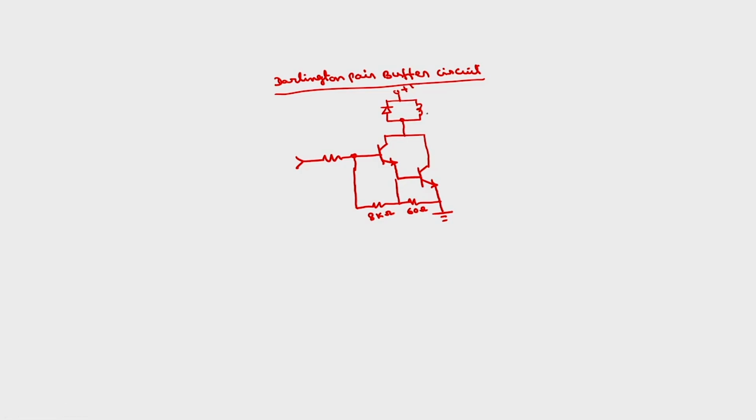This can be either a solenoid or coil, a relay or solenoid. Depending upon the voltage required for the relay, we will choose this V. That is why I have written this as V. This may not be 5 volts, you can take a higher value also. This you have to take from the output port of 8255.